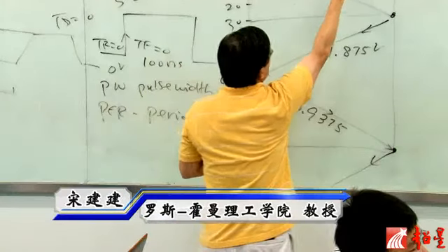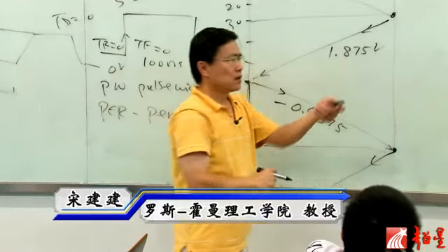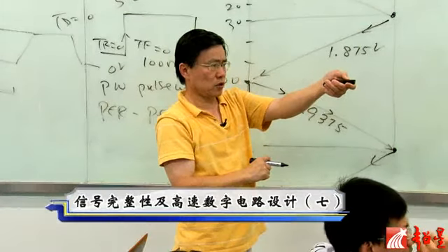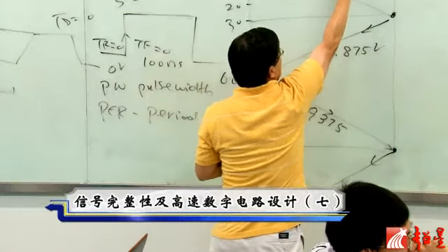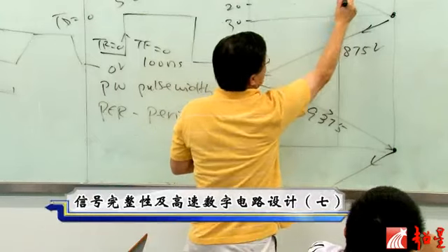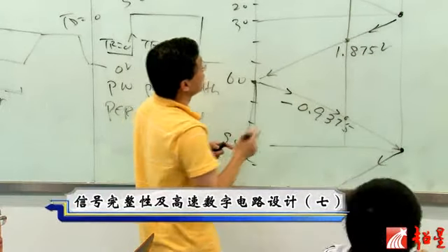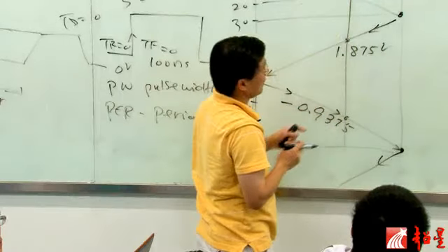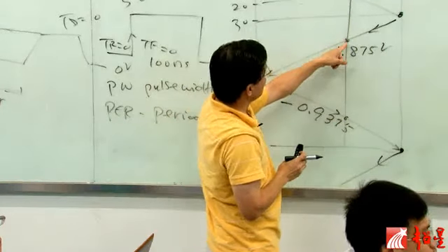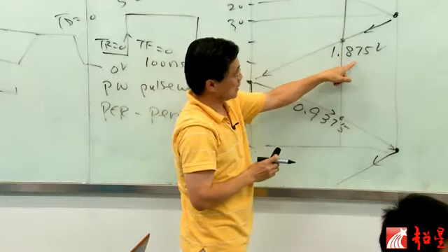What we need to do is, this is a 10 nanosecond point, this is a 20 nanosecond point, okay? That point is a 20 nanosecond location, right? So we'll just draw a straight line here, and then just add these voltages, okay? So basically, before 20 nanosecond, that voltage is 0. At 20 nanosecond, we have 3.75, okay? And then at 40 nanosecond, this voltage is added to it.